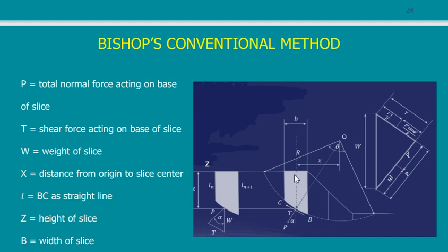In this method, he takes each body, he puts the forces on the body, and the force that will cause stability will be the force that will close the shape. Whether the shape is a triangle, rectangle, any shape, the closing force gives the value and the direction. If I have here a force in this direction, equal to this value, it will cause stability for this portion.